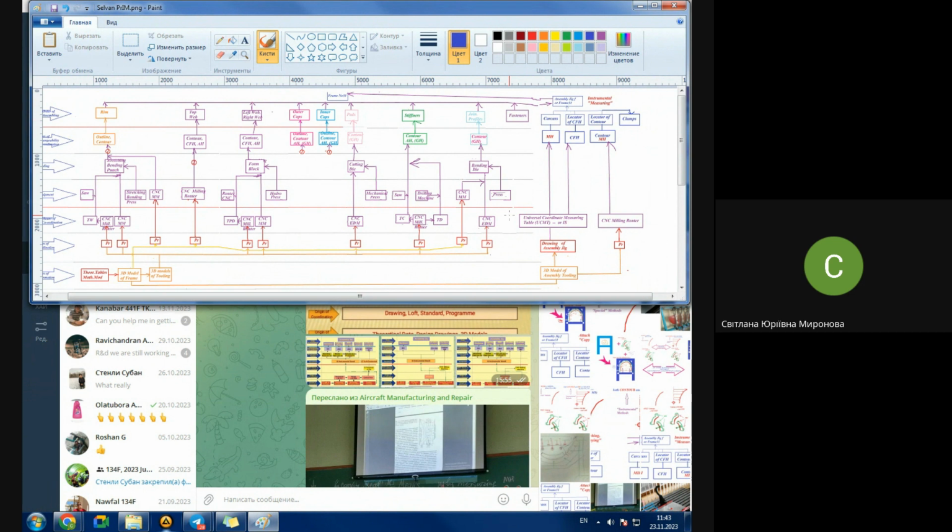We worked only in the right portion of the diagram where it comes about the jig. And in this portion we had the same set of locators and clamps, skeleton carcass, locators, and clamps. At the bottom, we had the same 3D model of tooling, and depending on what we have chosen, to produce a template and attach everything to the template, it's the program template method, or to measure position of jig elements, we have developed two different diagrams of coordination.